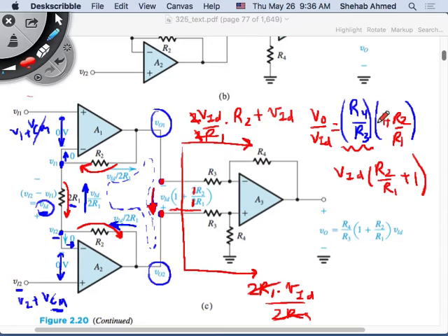I'm able to control the gain of the front end using R2 and R1, and they will not affect my common mode rejection capability. I'm able to control the gain of the second stage to make it low, so that I do not lose my input impedance for the second stage of the amplifier. I don't get how you fix this. Which one? The first problem? The second, our input impedance?